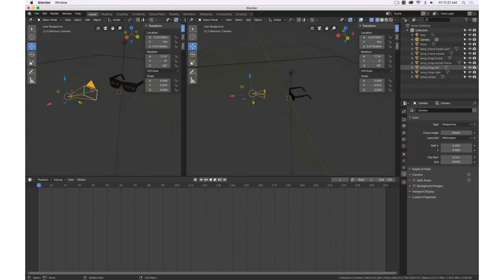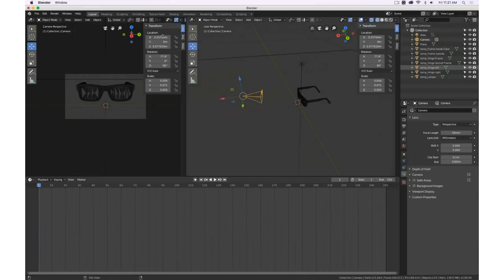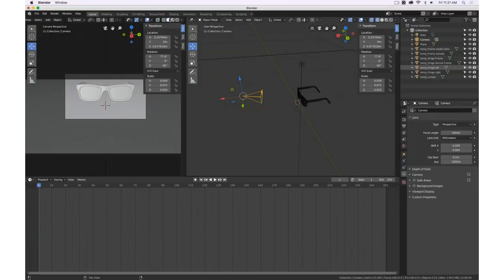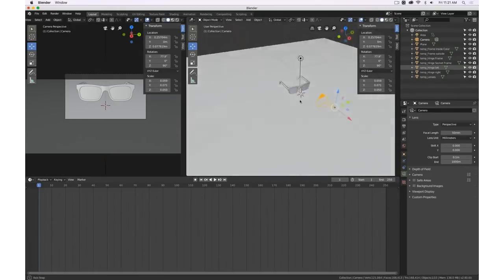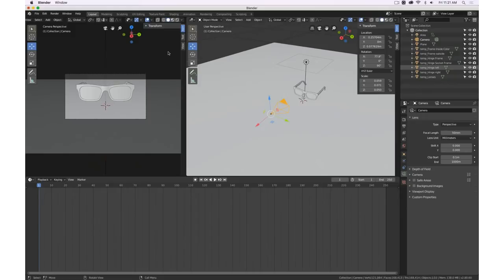Now with this camera selected, I can go to camera. Ta-da! And middle mouse button, click and drag. We set this to shaded. Here, shaded. So here now I can see my scene. I can scroll around, and here I see the rendering. This is actually very useful. Okay, very good. Let's press N. With N, you can show and hide the property. With T, you can show and hide the toolbar. And we're actually getting ready to do our first rendering.